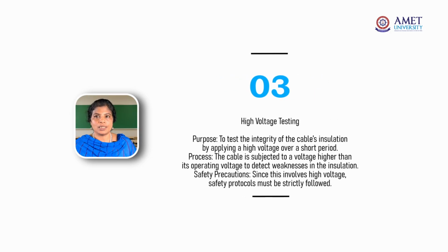Then high voltage testing. The integrity of the cable insulation is checked by high voltage for a short period. The cable is subjected to a somewhat higher voltage than the operating voltage. We have to take some precautionary measures while handling this test, because we pass high voltage.